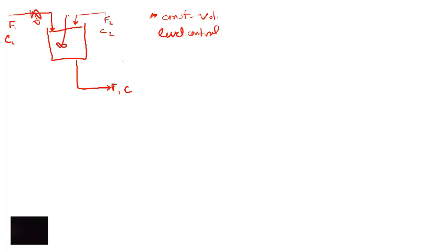We'll maybe also assume constant density and some other things, and we'll introduce those coming up. We can write the transfer functions for the process and for the actuator. We might have a composition sensor on the outlet, and we could do the transfer function for that. It would probably be a dead time type model.